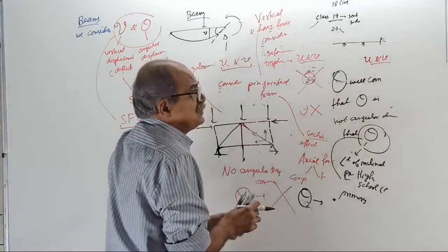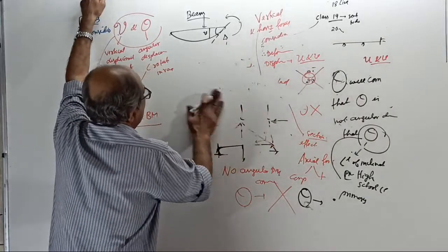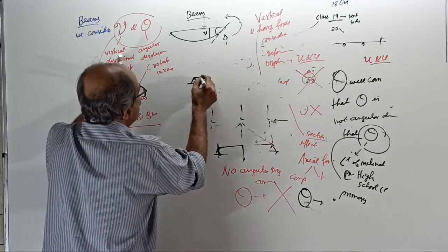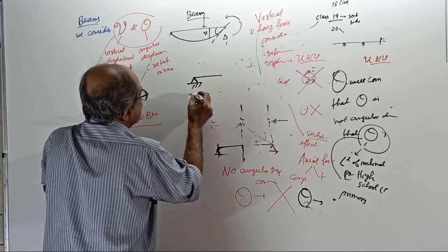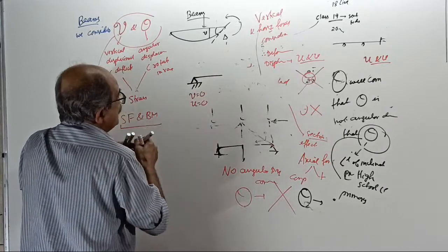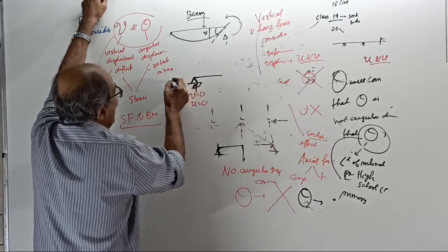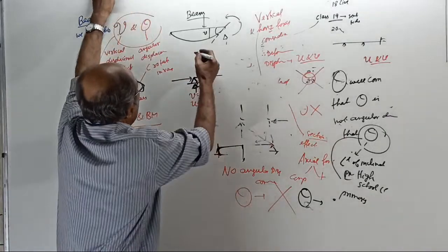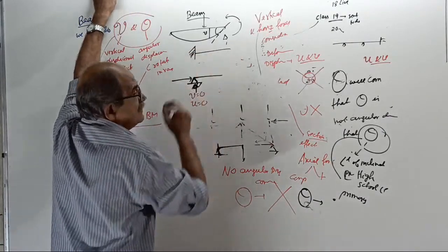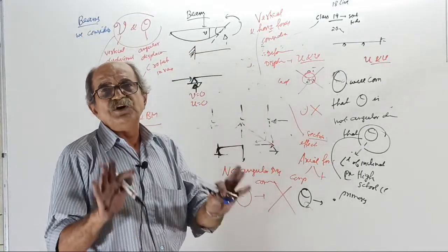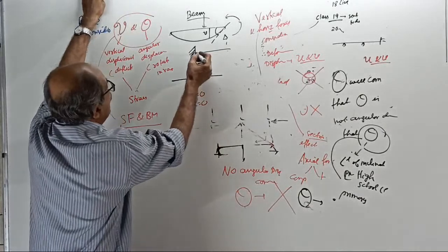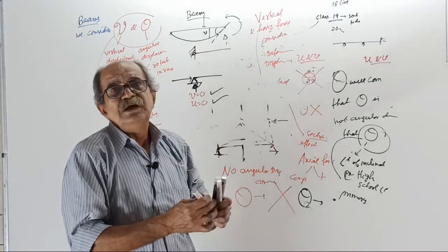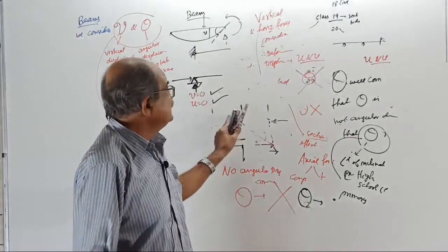Okay, now before starting, see there. If there is a hinged support, it has neither vertical displacement nor horizontal displacement. It can give vertical reaction and horizontal reaction. Reaction comes to prevent the displacement. Actually here the word fixed is not there. If the question says fixed, it is the same as hinge only, no effect. Now, this is clear. A hinge cannot move, it can rotate. Rotation, we are not bothered.